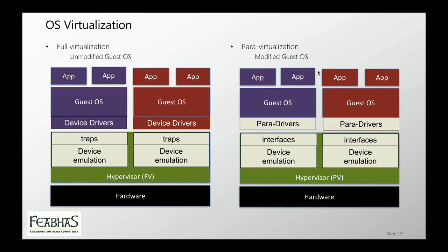So if you've got networking support, you might have Wi-Fi support on your target hardware, then you want your guest operating system and guest applications to utilize Wi-Fi as well. But that means that there may be a translation from the device driver for the guest OS to the actual device driver required by the hypervisor to drive the physical hardware. Some are very clever. They can reutilize and repurpose the guest OS device driver if the hypervisor is sharing certain common technology with the guest OS. And obviously you see this a lot with Linux-based systems, so that there's a closeness between the driver models.